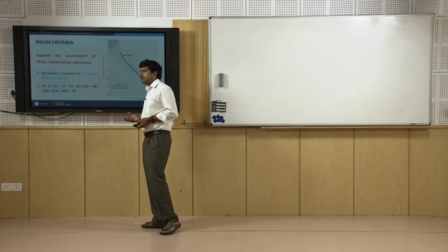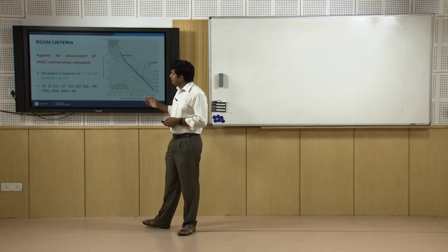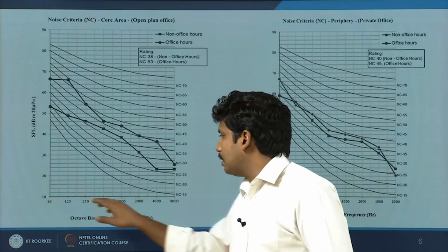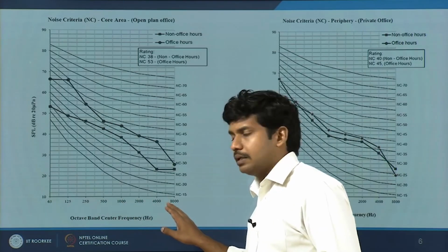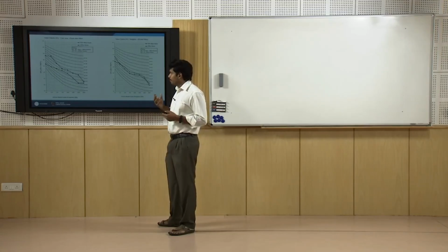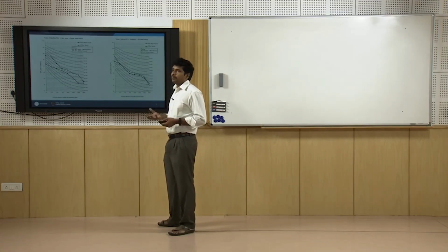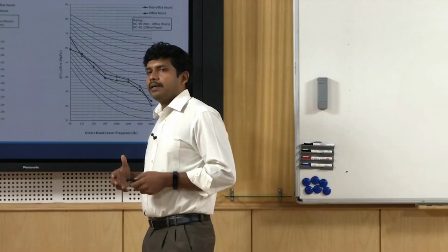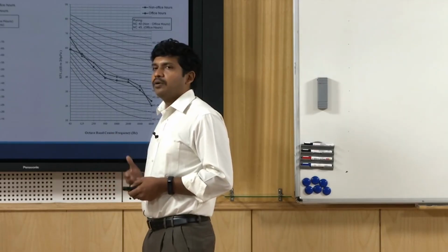There is another version of defining background noise level. If you closely look at the previous graph, you had frequencies ranging from 63 Hz all the way to 8000 Hz. Typically if you want to understand what an air conditioning system causes and its impact on the noise level: an air conditioning or HVAC system comprises fans, pumps, motors, air handling units, the mixing turbulent sound, plus the passage of air also causes turbulence, the throw of it. Together there is an escalation in the indoor noise level.